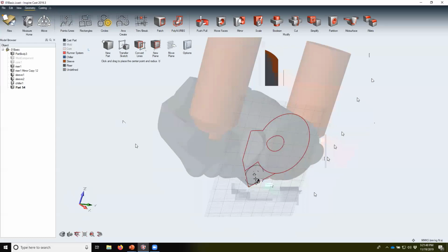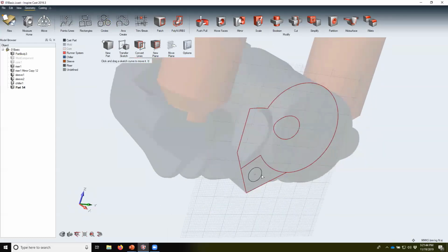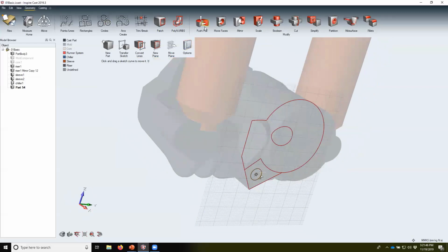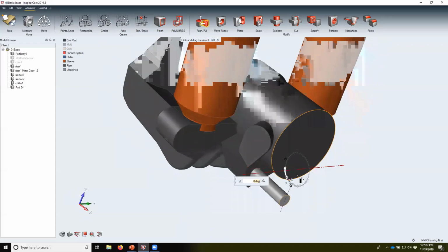So I'll put just a couple millimeter diameter. We're going to use 8 millimeter for the opening. And I can use some of the geometry modeling tools directly inside of InspireCast. We don't have to go to our SolidWorks modeler or other CAD modeler to do this. I can just simply drag things. It works kind of like SolidWorks' Instant3D, if you've ever used that. And I'm going to revolve this guy around an axis. Let's call that 90 degrees this way.